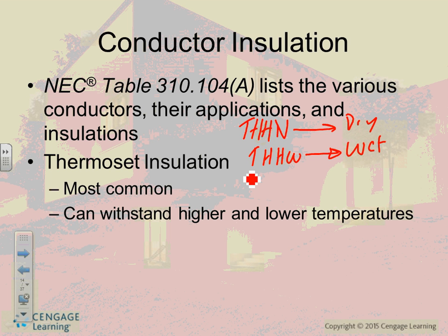Yes. Or dry. Okay. So there's a cable that says, guys, THHN slash THW. Where would you install this cable? Okay. That's what a lot of contractors will have, this insulation, which says THHN slash THW. Do I care if it's outside or inside? Okay, so that's basically the most common ones. This table, guys, has tons and tons and tons of others.